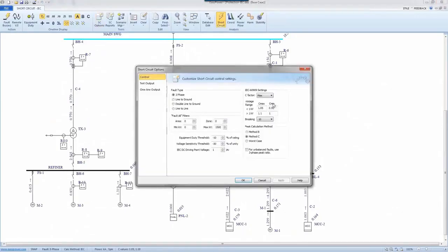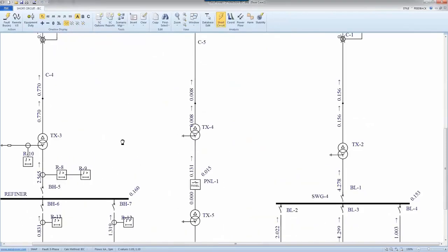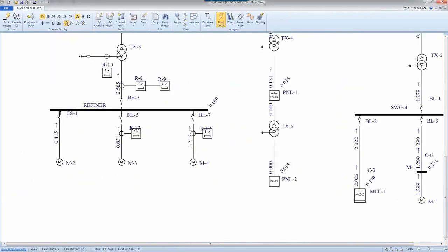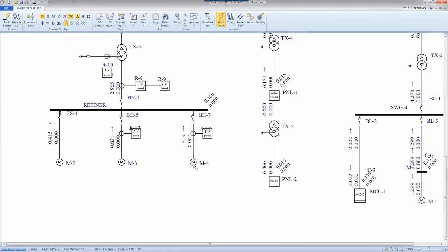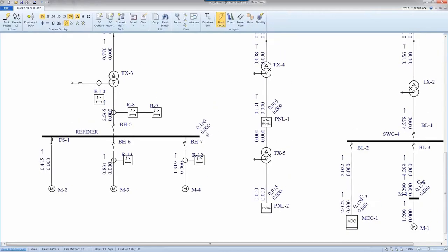So let me just go back here. I have C factor max here. I have a symmetrical fault, and I have a motor. And I'm going to look at the steady state value. It looks at the steady state contribution from this source, which is a close to fault source because I see decay here. So I turn this one off again, and there is no steady state contribution. Well, understood. Then the rule and exception to this rule is that, number one,